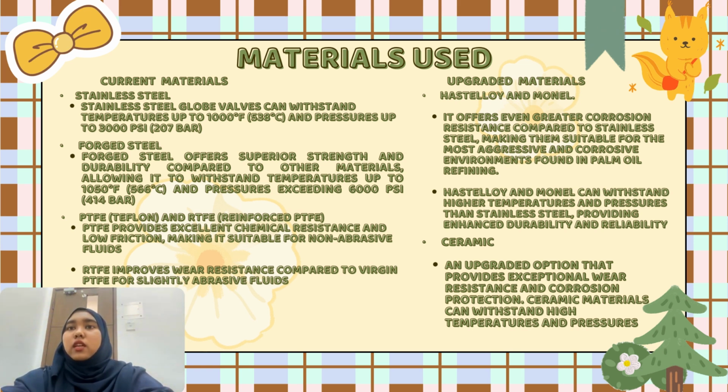The third is PTFE, Teflon, and RTFE, reinforced PTFE. These materials are preferred for the seat components in globe valves used in oil refining. PTFE provides excellent chemical resistance and low friction, making it suitable for non-abrasive fluids, while RTFE improves wear resistance compared to virgin PTFE for slightly abrasive fluids.